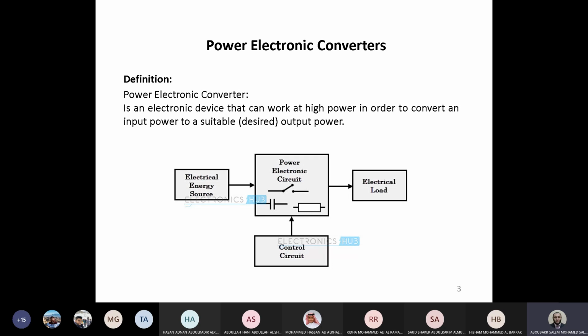For instance, when we discuss DC motor, we need DC supply with certain voltage magnitude. When we discussed AC machines, like induction, we need to have certain voltage and frequency at certain times to control our machines. Also, when we discussed stepper motor, for instance, it needs pulses or volt-like pulses, not like a constant DC supply.